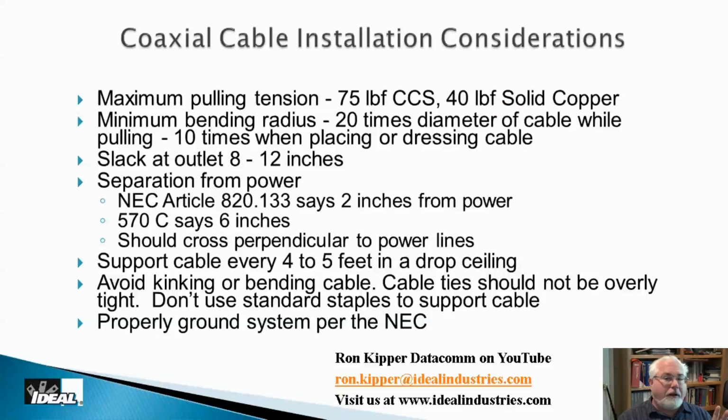Okay. And solid copper at no more than 40 pounds of force. Now, how do you measure that? Well, you know what? Nobody measures it. But you kind of have an idea in your mind as an installer. If you're pulling on the cable a little hard and you stretch it a little bit, like I tell guys, if you ever pulled Romex and the outer jacketing of the Romex is like 3 feet longer than the copper inside, well, you pulled on it a little hard, but it still works. But you wouldn't want to do that to coax. You'd probably damage the cable to a point where you wouldn't want to use it.